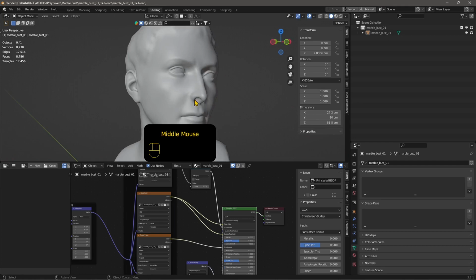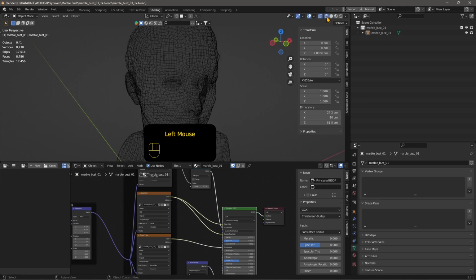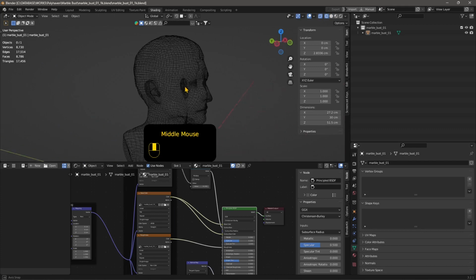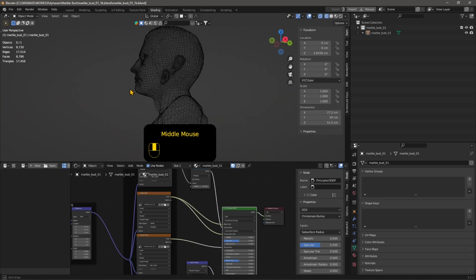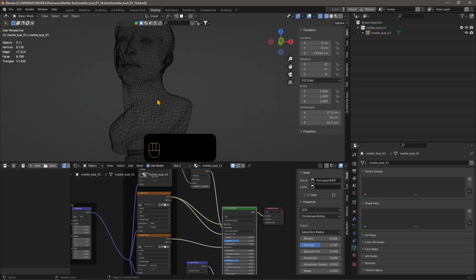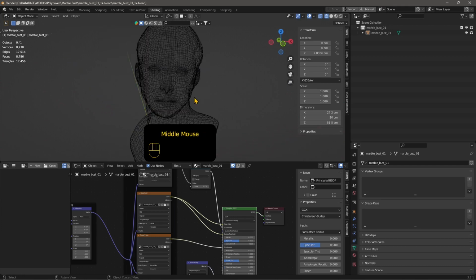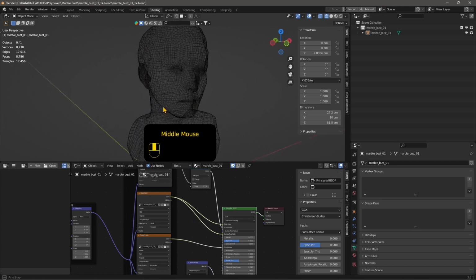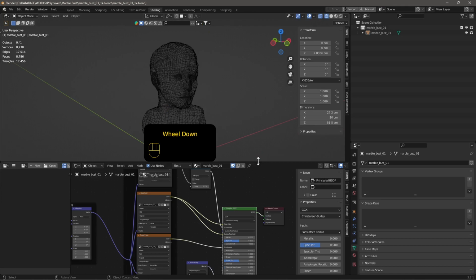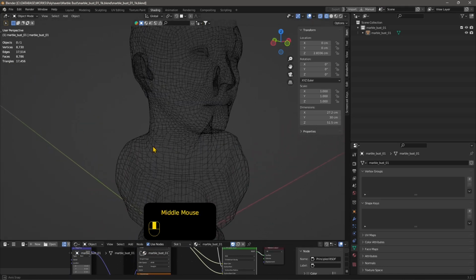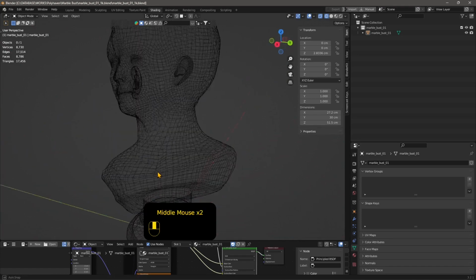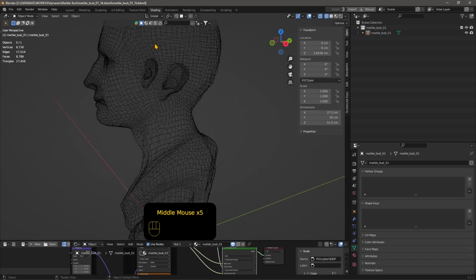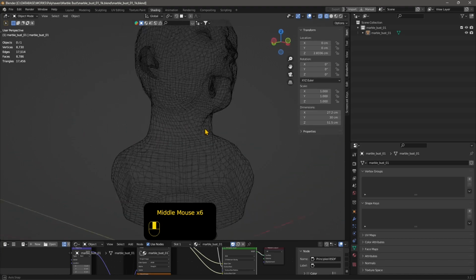And this is smart because this is optimized. So if we go in the wireframe mode, we can see that where we have more details, we have more polygons. And the areas that are larger and with less details, they have fewer polygons. And this is a smart way. It's kind of like when we use Dyntopo, when we create more polygons where we need them, not everywhere. So don't increase the number of polygons everywhere, because you just need to increase it where they are needed. And another thing I would like to point out is that this is a really nice topology, a really nice structure. It's clean, it's neat, it's not messed up. So everything looks nice and